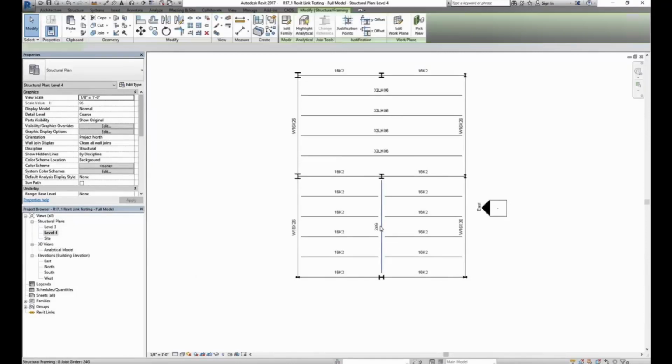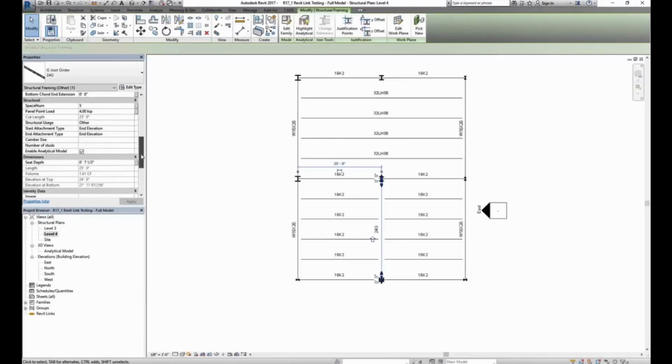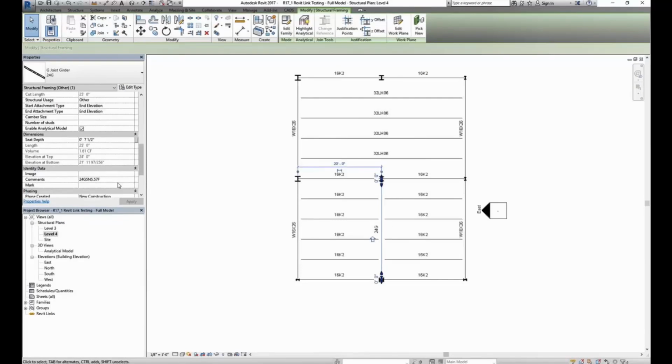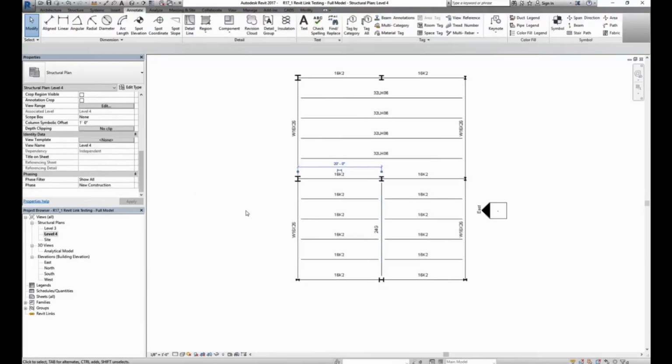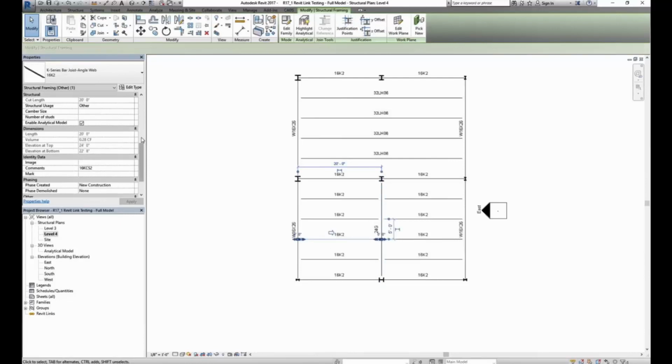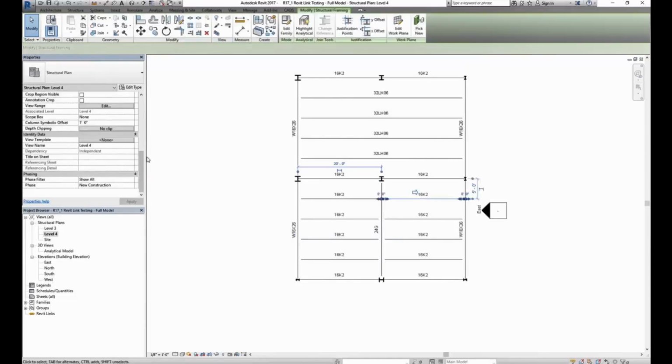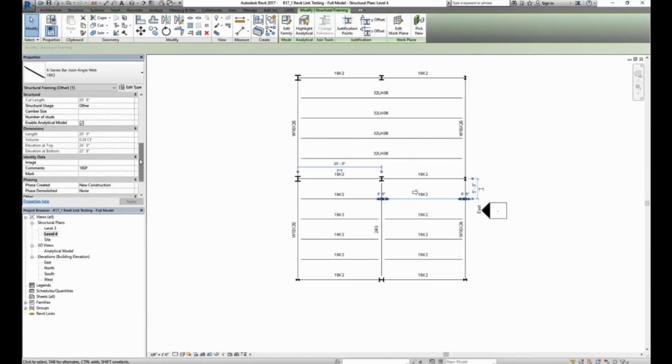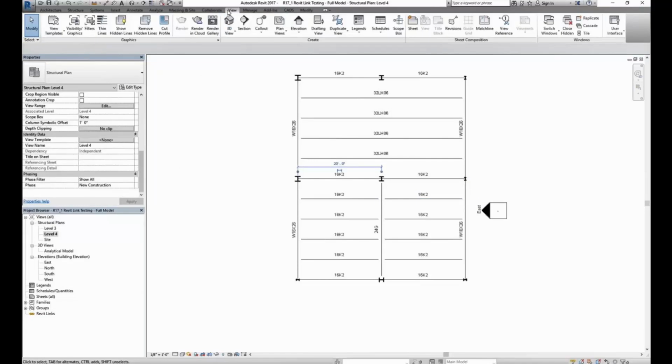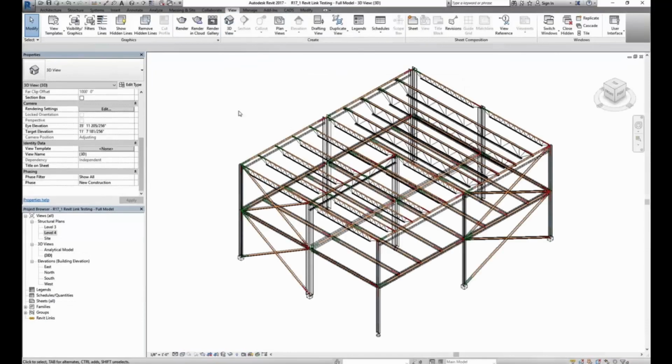If we click on the joist girder here, we can see that it's a specific joist girder, and it has specific information in it, the number of members that are connected to it, and also the load. We can look at a standard joist or a KCS series joist in this matter, or even a special joist. All this information is available to look at based on it coming from the model in SCIA Engineer. So you're not adding this from scratch, you're adding it by just using the BIM annotations.